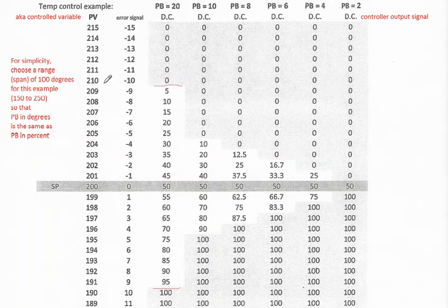And you can see it's when you hit 10 degrees above the set point, you're now from there on just going to be applying 0. Your control signal is a big 0, which is basically off outside the proportional band, or fully on outside the proportional band if you're below the set point.